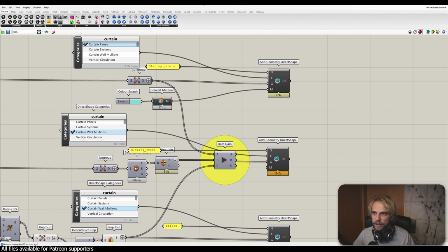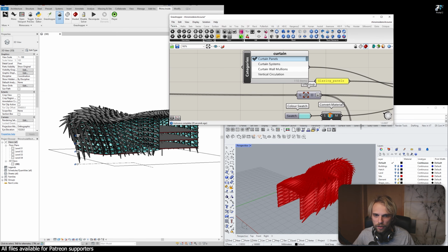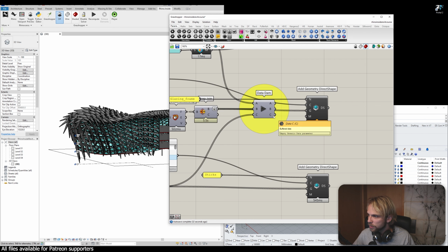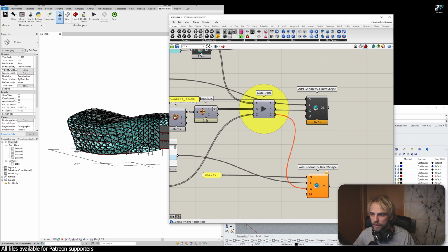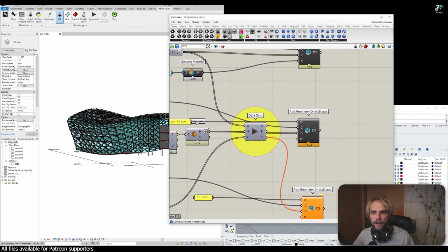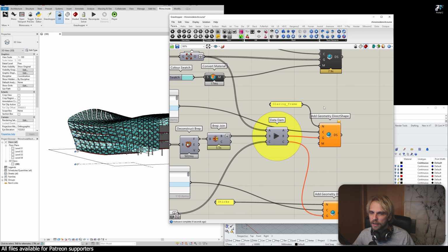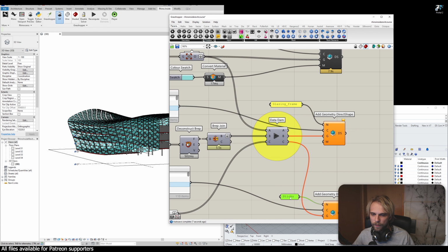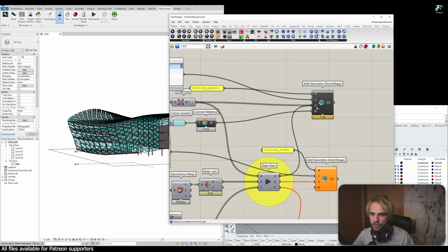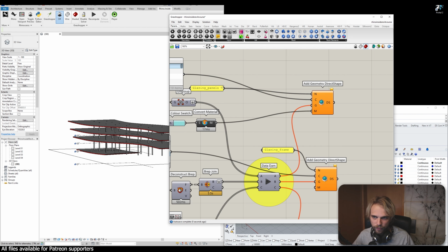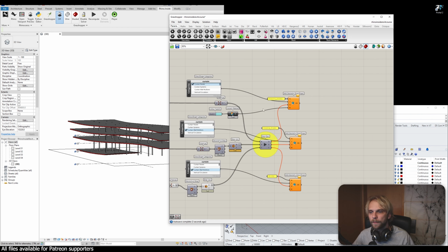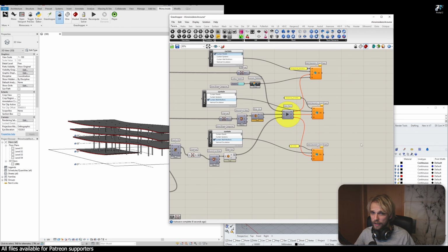And then from our data dam, I can actually show you this in real time. Output C connects to the geometry input of sticks. You can see that now this is empty because we didn't press the big play button. Then output B goes into our glazing frame input right here, and then output A goes into our glazing panels right here. Okay. So now you can see the facade is gone, and that's because we are not letting information through.